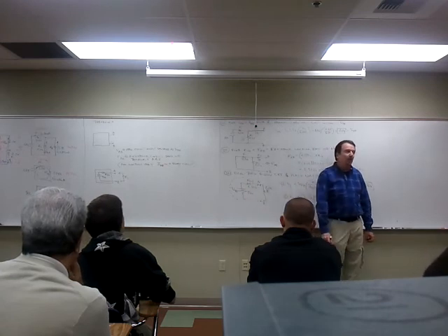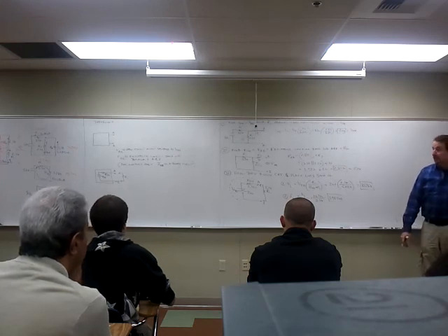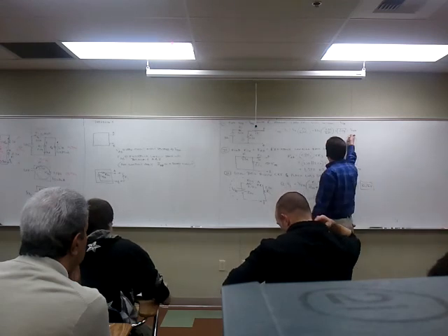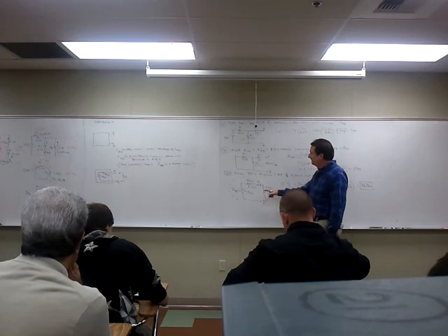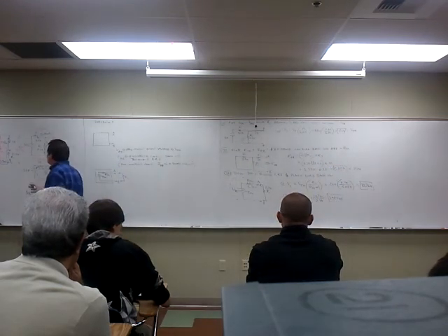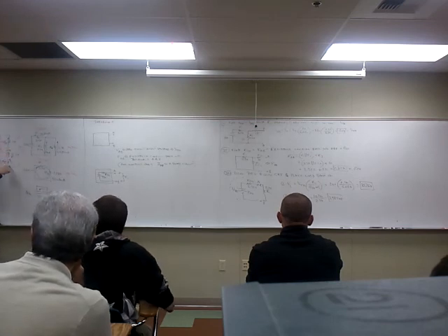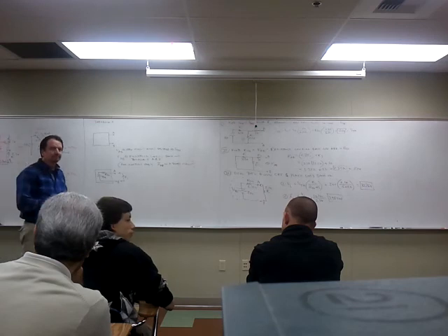That circuit is always the same. It's a voltage source and series resistor. So this 20 volts that we found, we label this 20 volts. Then we have to have the series resistance. What does that series resistance mean? It says, what are all these components looking like if I put an ohm meter from there to there? If you put an ohm meter from here to here, you would measure the equivalent resistance looking back into these terminals.